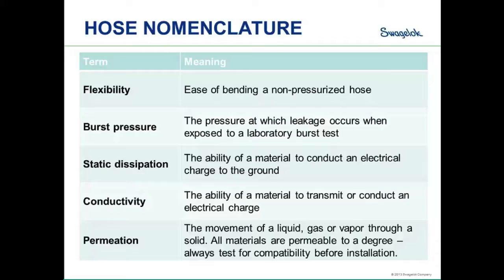Conductivity. Conductivity is a measure of how well a material accommodates the transfer of an electrical charge. So this is a little bit different versus media concerns, where static dissipation could be kerosene, where there's a concern that you could have an explosion with the material. Conductivity would be more if we had a cherry picker where we're working around electrical wires, and we were concerned that if we were to brush up against a wire, that electrical charge would transfer through the hose. A conductive hose would allow that charge to transfer. Non-conductive would not.